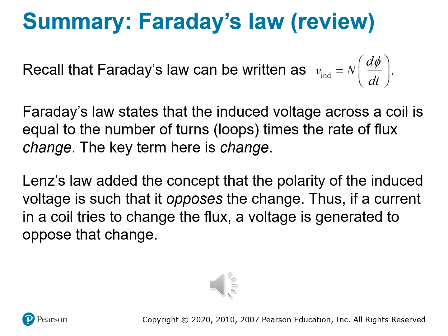Lenz's law tells us that the polarity of the induced voltage always acts to oppose the change in magnetic flux. So if current is increasing, the coil tries to resist by generating a voltage in the opposite direction. If current is decreasing, the coil fights to keep it going. It's, again, electromagnetic inertia. Coils don't like change. And this explains why you get a voltage spike when you turn off current to a coil, or why inductors slow down current changes in power supplies, or how energy is stored temporarily in a magnetic field. It's all Faraday and Lenz at work.